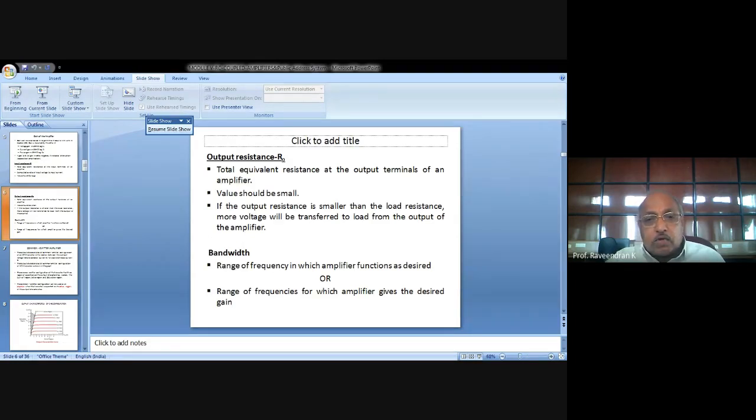This transistor will have its DC operating conditions only through this VCC, which is connected here. That will never change, and it will not affect the subsequent stages because the coupling capacitor is here. This voltage will not reach the next stage because it blocks the DC. It allows only the amplified version of the alternating signal given to it to pass.